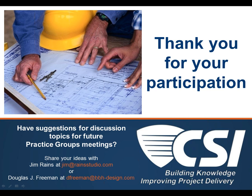You do not know at that point, unless you've had a conversation with the contractor, why he has made that change. It could be because of erection tolerances, construction tolerances, using a different product than the one that was the basis of your design, or any other number of reasons. And when you change that dimension, you are taking responsibility for it.